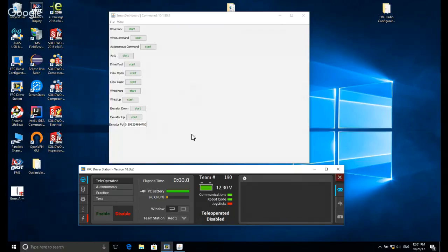So to do motion profiling, you have to add all of the motion profiling stuff, like obviously you need the code to do that. And then after you do that, all of the motion profiling libraries have a motion profile execute method. All that does is you give it the motors and you say go, and it'll run a step of the motion profile. So all you do is run that step code in a command for the drivetrain, in the execute method, and it'll just go and run it.